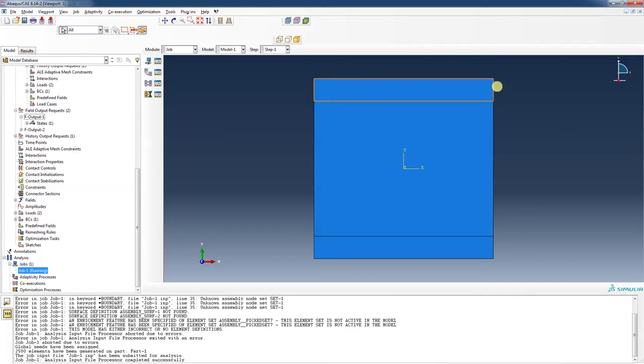Now due to the locations that we put our load, we would expect to see our crack show up kind of down in this corner. If we're pulling this way and pulling up this way, at some point in time, it's probably going to initiate over here. It may not be at the exact left edge where it initiates because we have the over-constrained condition on the boundary conditions down here. In a physical model, that may or may not be what you want.